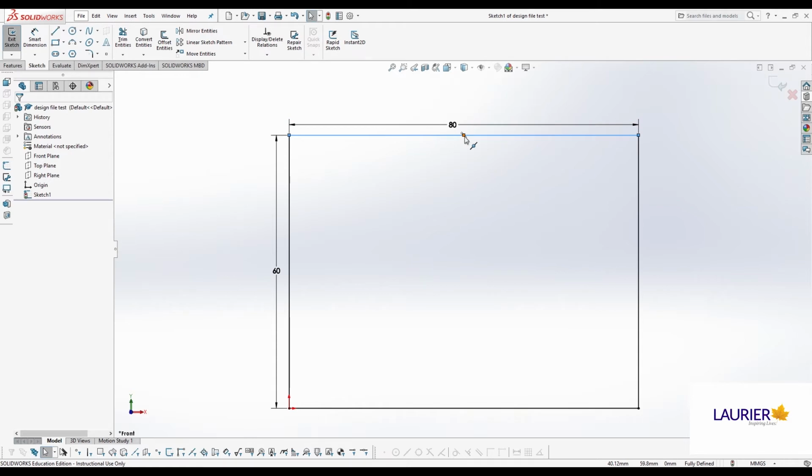of that line. The point is, if you get an error that tells you that you're overdefined, you need to go look and see what would have to become untrue for you to edit that dimension. And then you can either delete the dimension if you didn't want to change the other thing, or you can delete whatever property is locking that other thing into the shape or size that you don't want it to be in. And you can go into the properties of that, delete it, and allow that to freely move. We've got our rectangle, and we can exit sketch.